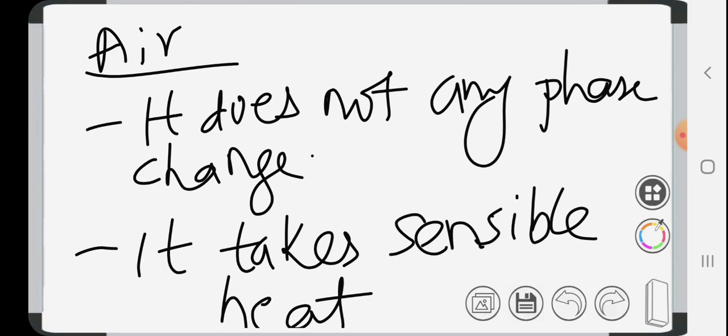So students, hope you understood the idea. So the power required to operate the unit will be higher in this case, right? Because the amount of sensible heat that air can absorb or reject may be very less compared to latent heat. So we have to operate this system or cycle at a higher power. Higher power means lower COP. So that is why the air system is not practically used. But just for the sake of study, we will be studying the air refrigeration cycle.